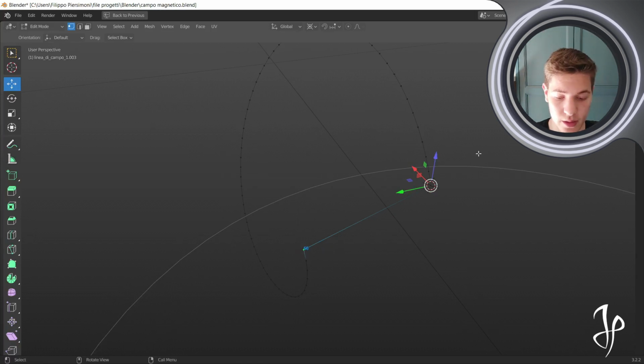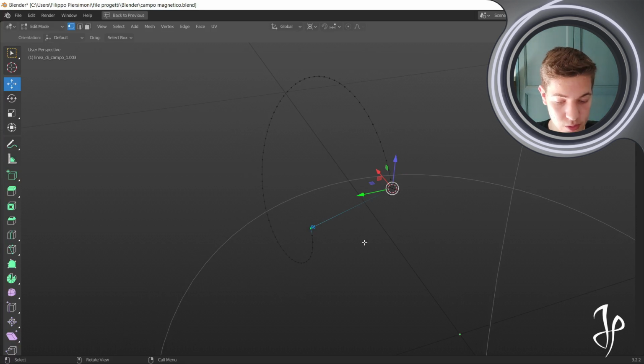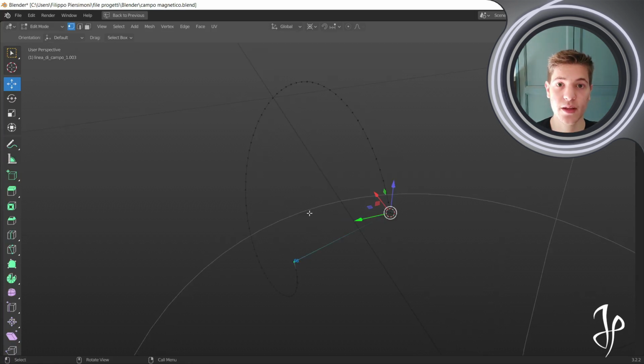So what you want to do is translate this vertex from here to here, so that you can close the polygonal, and so you can reduce the error of the representation of the fill line. So basically the uniform settling method starts from the hypothesis that the error accumulated by the polygonal construction, so by the algorithm, is linear throughout the construction of the polygonal line.